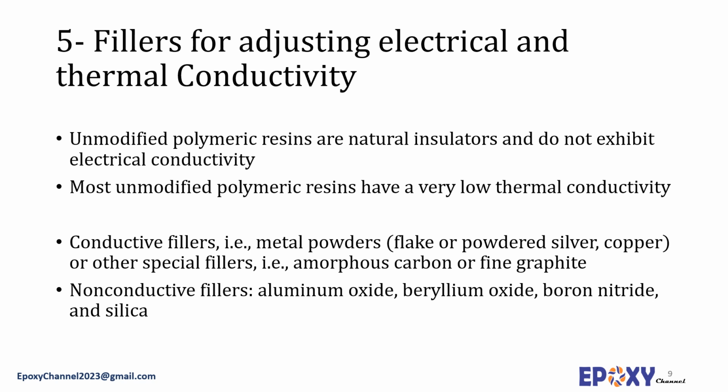Electrical conductivity is of course important in adhesives that must make electrical connection between components and in adhesives that must provide electromagnetic or radio frequency interference, EMI and RFI, functions. Thermal conductivity is also important in highly integrated electronic applications where the heat generated by the components must be transferred to a heat pipe or by some other means outside the electronic package.